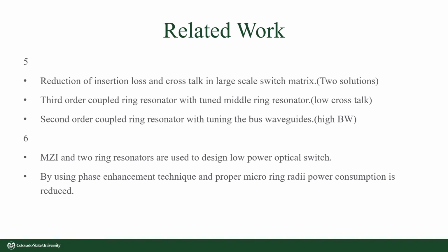Coming to the next paper, to design a low-power optical switch, an MZI and two ring resonators in the MZI arms are used. The relative phase change between the MZI arms causes the switch operation. By using phase enhancement in the micro-ring resonator, the power consumption is reduced compared to electrical switching techniques. By choosing appropriate micro-ring radii, the power consumption of the optical switch is almost independent of the propagation loss in the racetrack resonator.